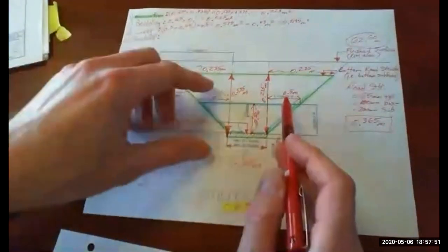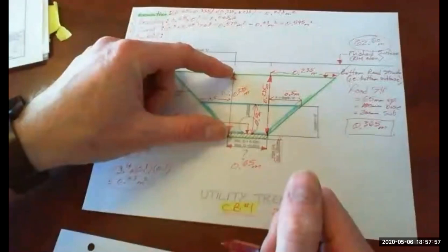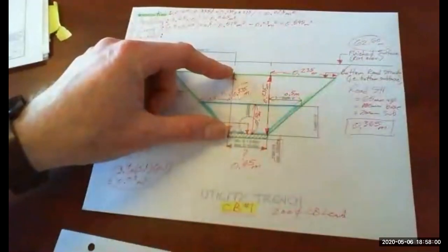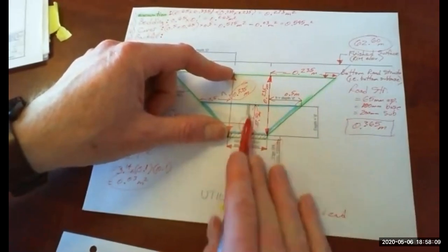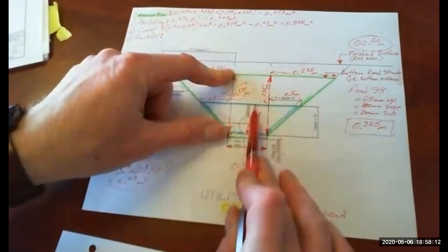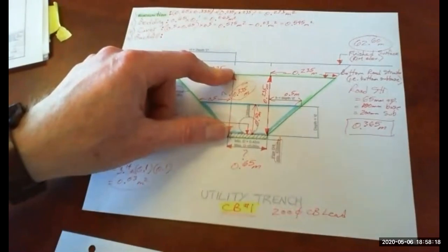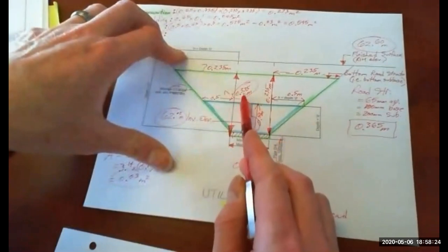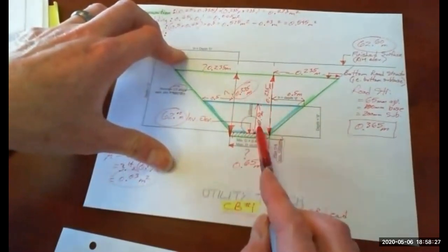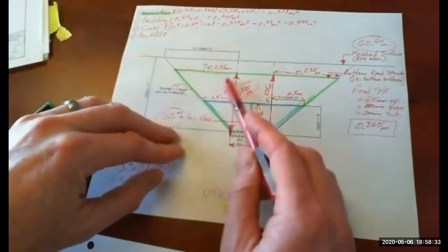So why do I say that? When we calculated our rim to invert and then our subbase to invert, we said we were 0.335 meters deep, right? So when we calculated our cover amount, we said our cover needed to be 0.5 meters deep based on this 300 above the pipe. This isn't drawn to scale, this cross section. So what that tells us is our cut depth of 0.335 is less than our cover depth of 0.5. So there is no backfill volume here.